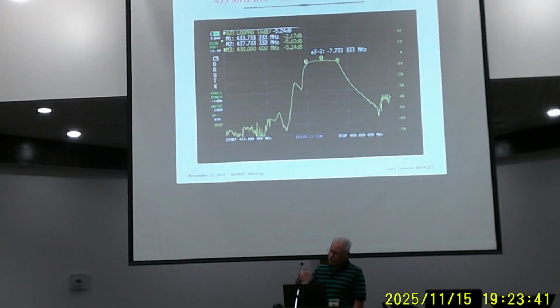And if you look on some of your tests, I think it says the bandwidth is at the negative 3 dB points. When a filter rolls off 3 dB on either side, that's where you calculate the bandwidth. So you take negative 2.2 and you add 3, I want to be at negative 5.2. So again, we got discrete frequencies. I moved those other 2 markers as close as I could get. And so that's the bandwidth. So it says that delta 3 minus 2, it's about 7.7 megahertz bandwidth with a 2.2 dB insertion loss.